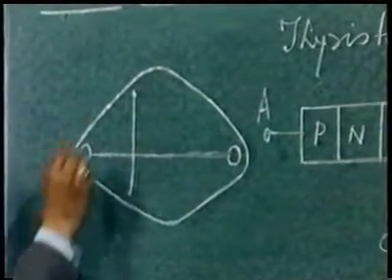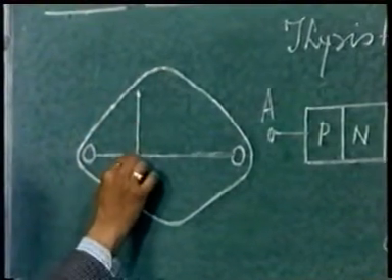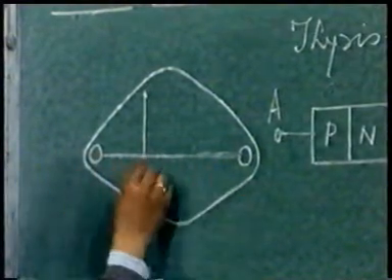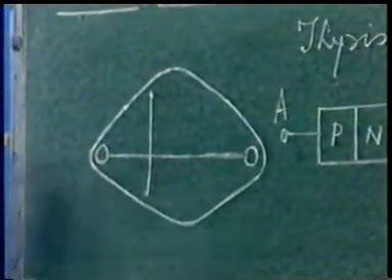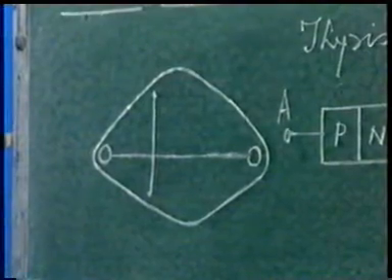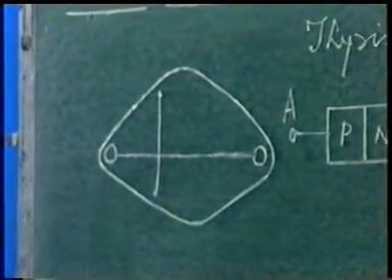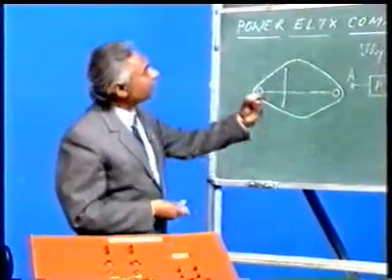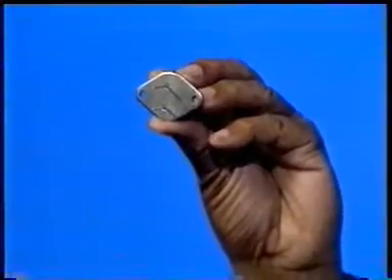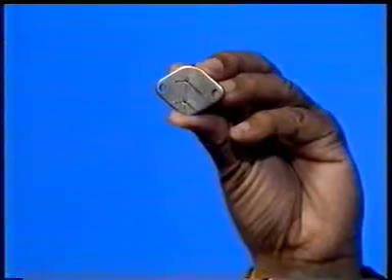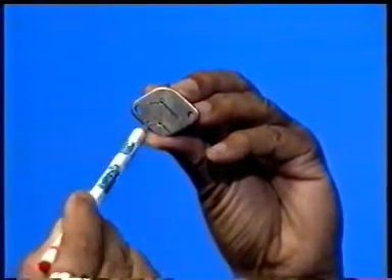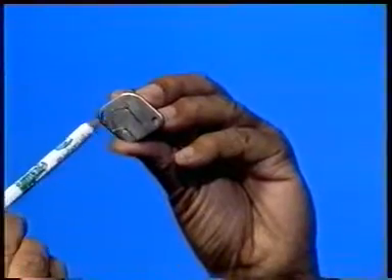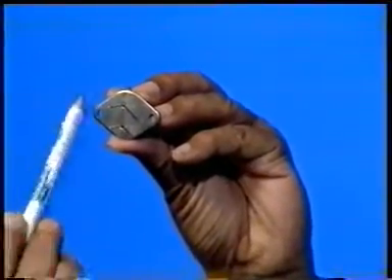If I see it minutely, from this center one of the holes is nearer and the other hole is at a larger distance. You have to keep this in your mind. Look here, this metal body SCR has to be kept like this. From this center to this hole the distance is more than from this center to this hole, and the two terminals are coming out.